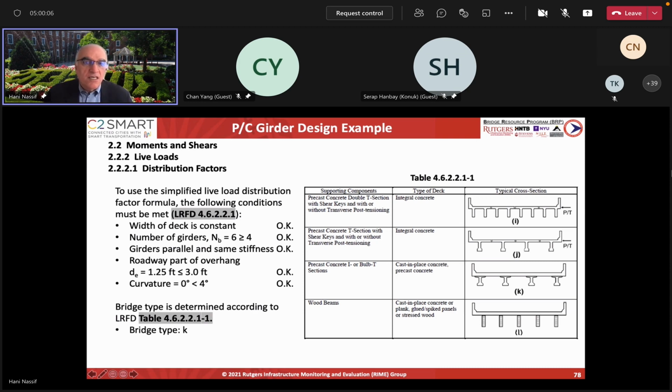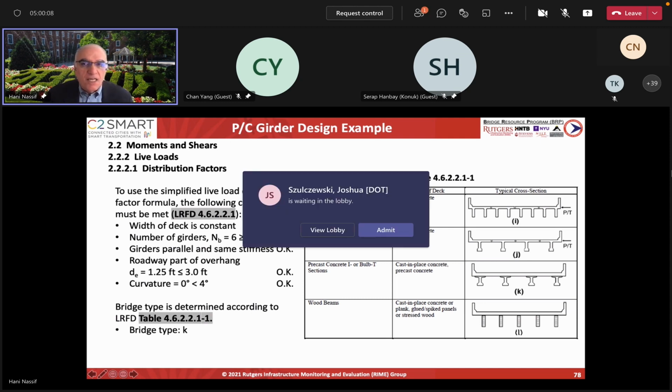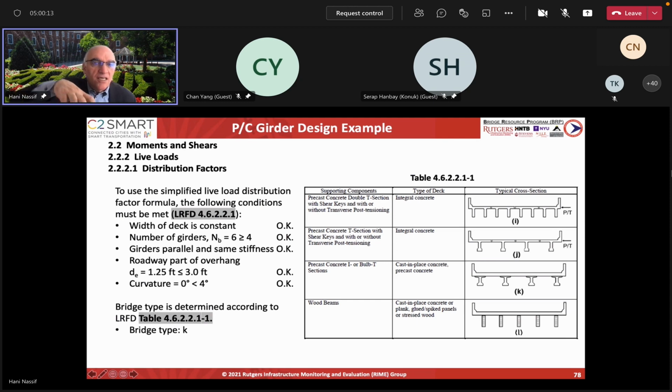You can take the larger spacing. In other words, if the truck moment is applied in the middle, and the average spacing between 9 and 12 is, let's say, 10 or 11 feet, then you would use that with that moment, because the distribution is happening at that location, going through that girder spacing if you take a transverse cross section.